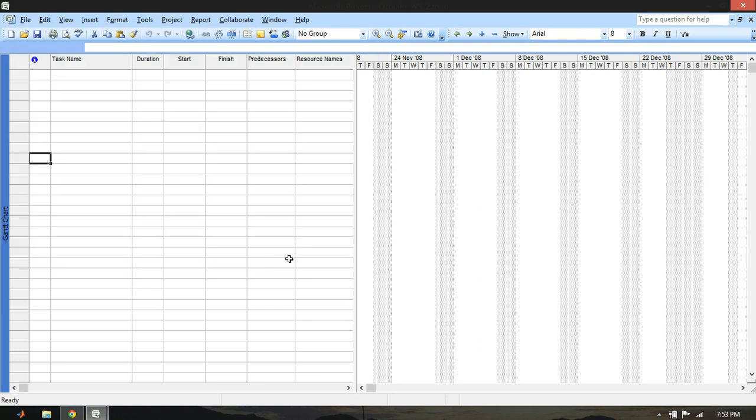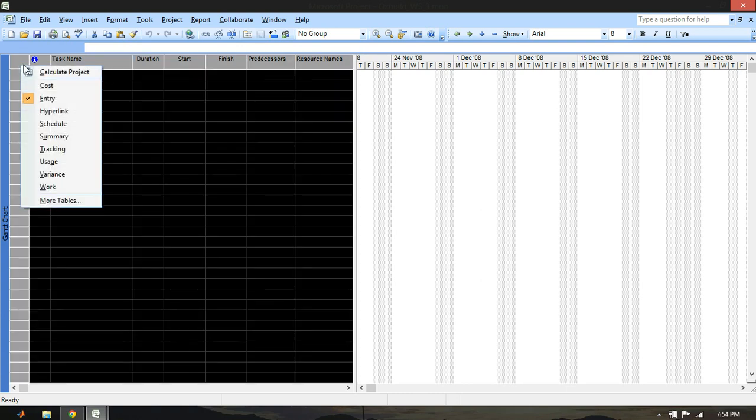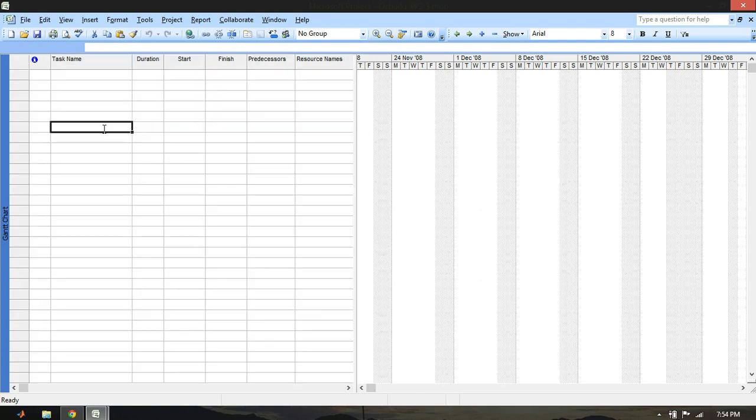And now we're on to 4. Okay, this is where it gets nice and not tricky, but just annoying, I guess. So first of all, let's set it up how they have it set out on the actual assignment sheet. Assign the 6-day working week calendar to the task information form. Double click the task.